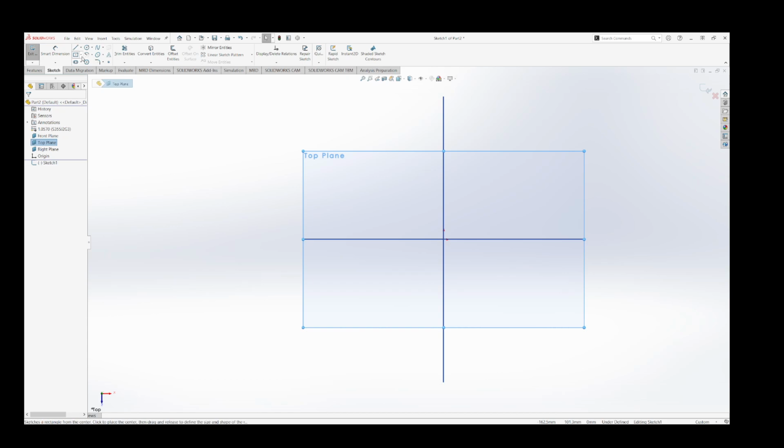I choose here the rectangle tool. By default, the rectangle tool is the center rectangle, but there are different types of rectangle tools. When you click on this little arrow next to the icon, you can see this drop down menu where you find 5 different rectangle tools. These all work in a little bit different ways, but for this one I will choose the center rectangle. You can test out these different rectangle tools if you wish. So I choose the center rectangle.